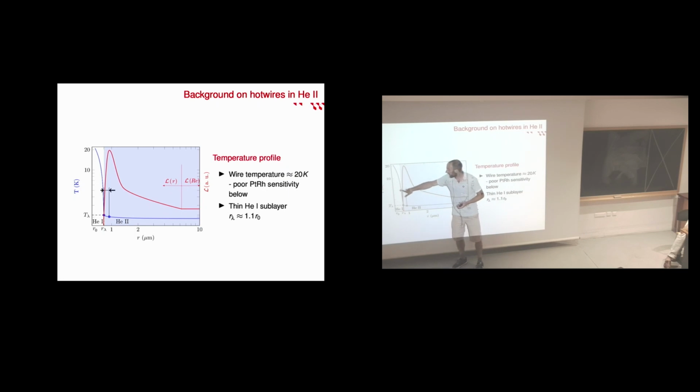I would not expect that it varies as a function of the velocity, because the sensitivity to velocity, so the heat flux that we have to push inside the fluid in order to maintain this temperature, is mainly what fixes the width of this peak, and the absolute value of this flux varies very poorly with the velocity.